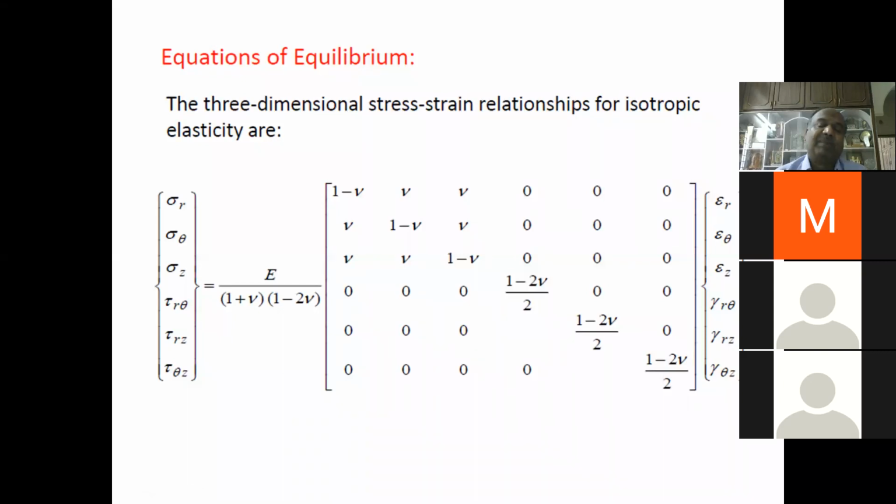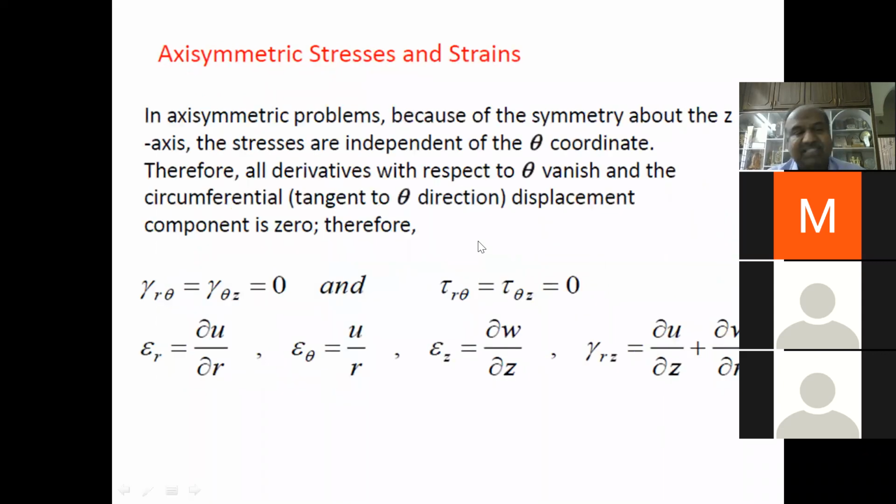in the case of the 2-dimensional plane cylindrical coordinate member. If you write the stress strain relationship, this is a D matrix for 6 components of stresses and 6 components of strains. Whether it is Cartesian or cylindrical, this D matrix won't change because it depends on Young's modulus and Poisson's ratio. The 3-dimensional member, whenever you write it in Cartesian or cylindrical, your D matrix is going to be the same, because stress equals D times strain, where the proportionality is the D matrix, the material matrix.